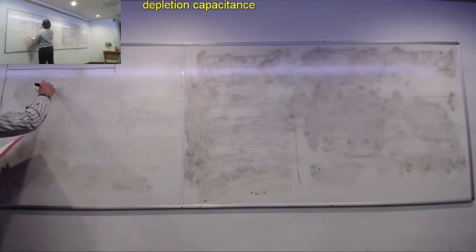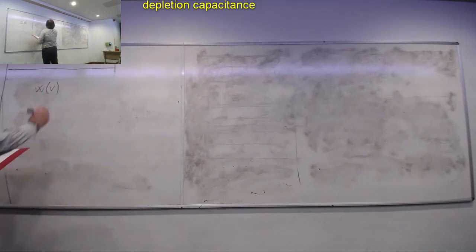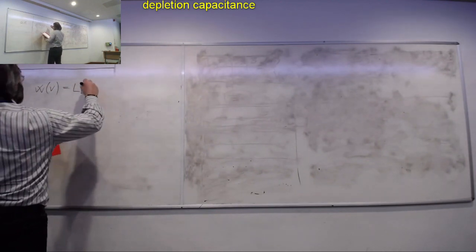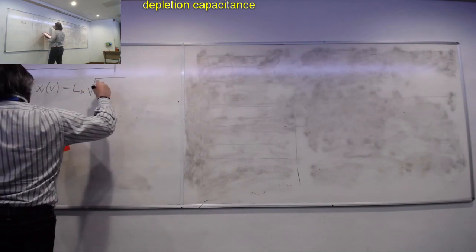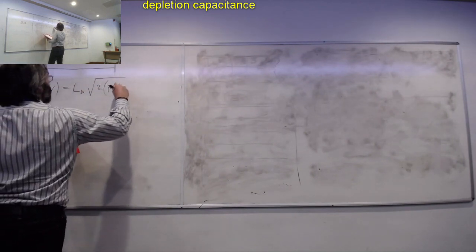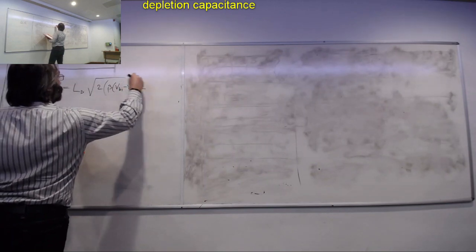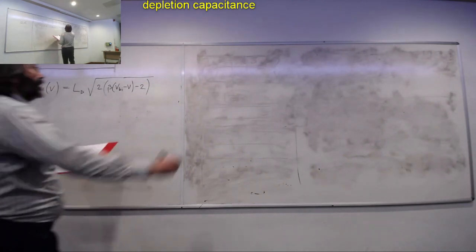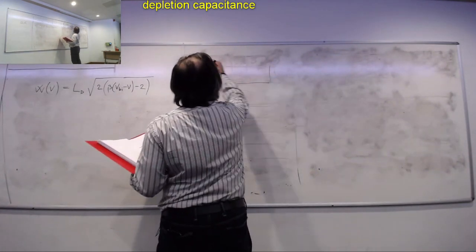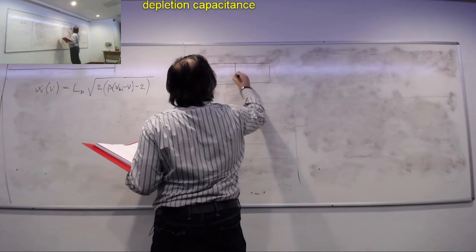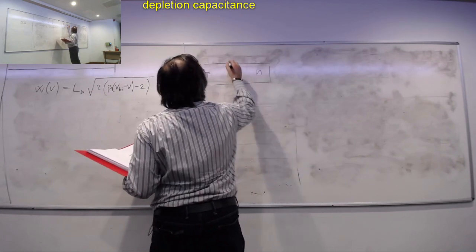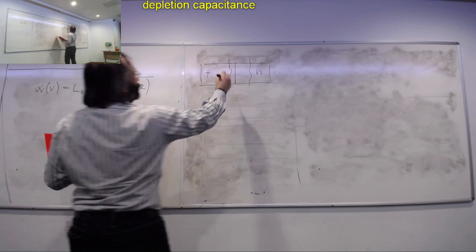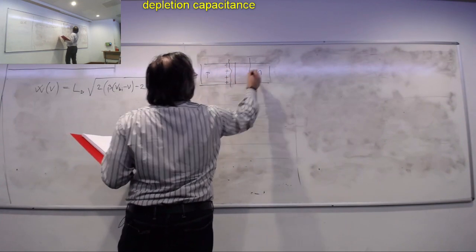We came up previously with this generic formula that gives us the depletion layer width as a function of the voltage applied externally, and it was this one here, VBI minus V, all in this parenthesis. Remember that the picture we have in our mind is that if this is my P side and my N side, there is a depletion layer that is keeping separated the free carriers here and there.